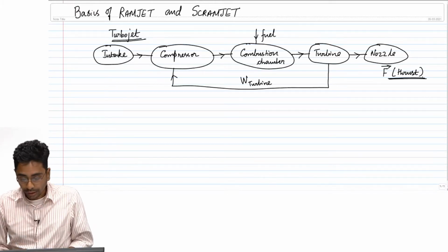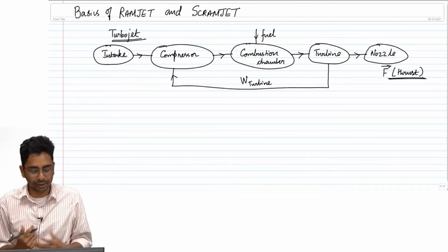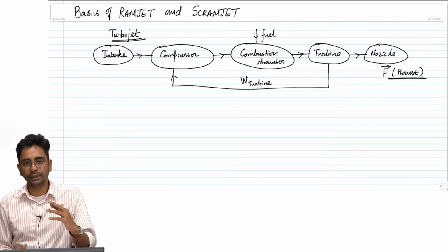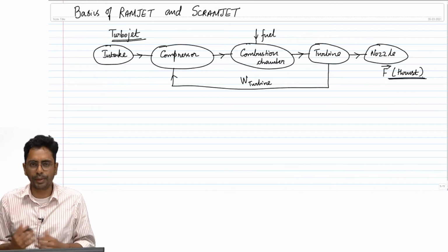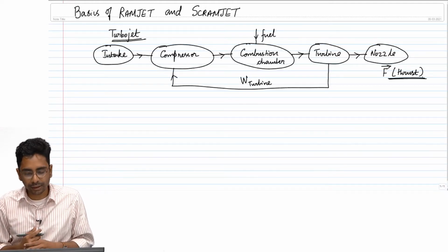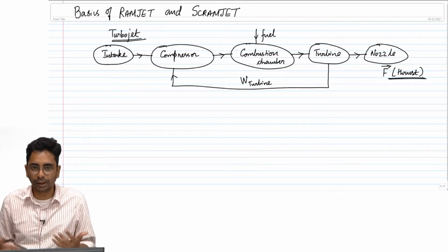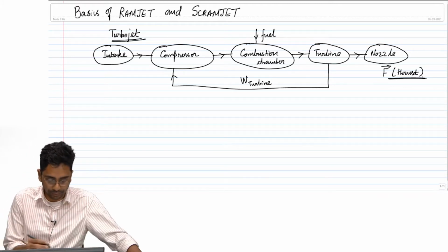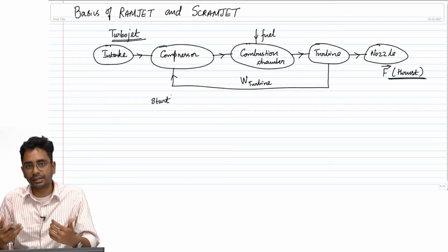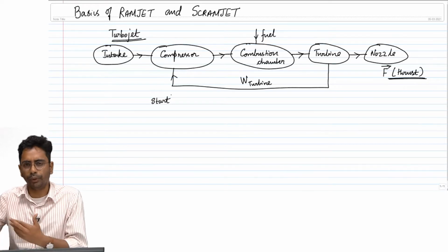Now, we all know that if you have an aircraft with a turbojet engine, you can start from ground at Mach 0, accelerate to maybe Mach 1, 1.1, 1.2, maybe up to 1.5, and the engine has a certain performance envelope for this range of Mach numbers. That is, you can produce a positive thrust to accelerate a vehicle from Mach 0 to about Mach 1.2, 1.3.